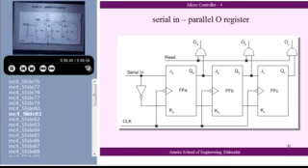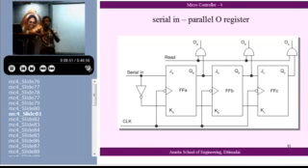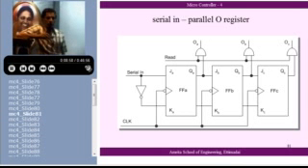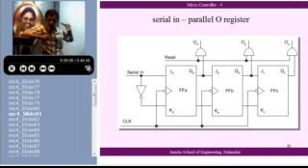I can do serial shifting. I can do parallel output. It's a crudest form of a communication terminal. I take a number of flip-flops. I have a data stream coming in on one line, 0, 1, 0, 1, 0, 1, 0, 1. I take 20 flip-flops, all the 20 bits I load into all of them. I do a parallel reading. I can convert any serial bit stream which is coming in and read it out as parallel data. Okay? It is a serial input, parallel output scheme.